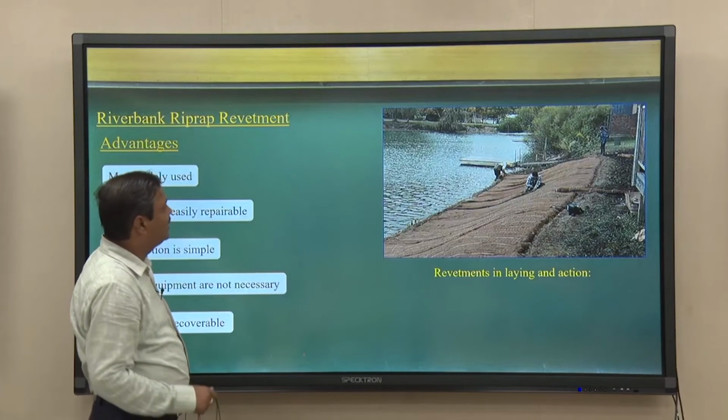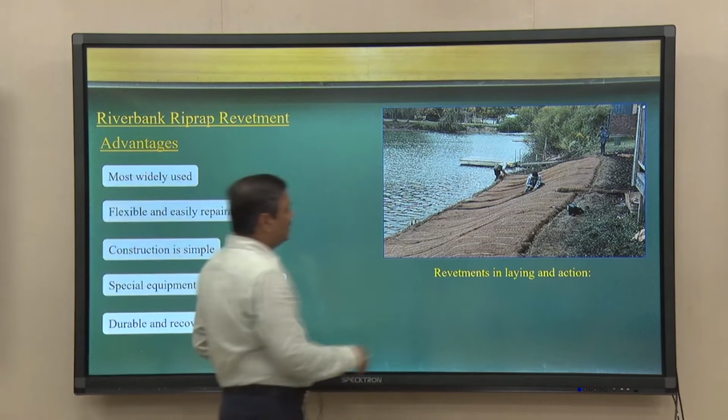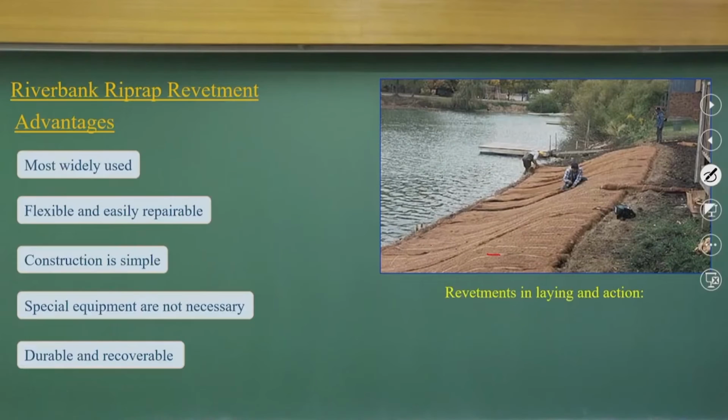Now, when you talk about river bank protections, if you look at this, it is a simple textile based river mattress. This is a small river, they can put textiles, jute type of materials, and just protect over the bank with the filters and all.